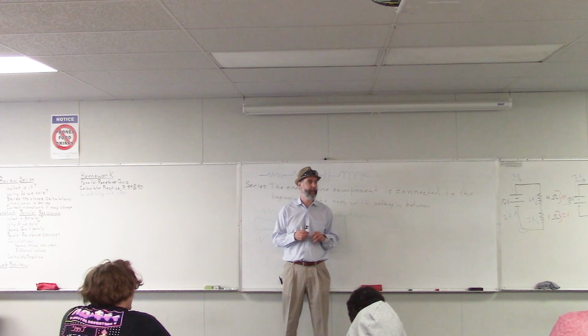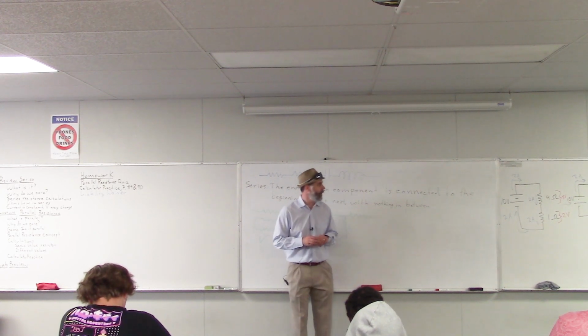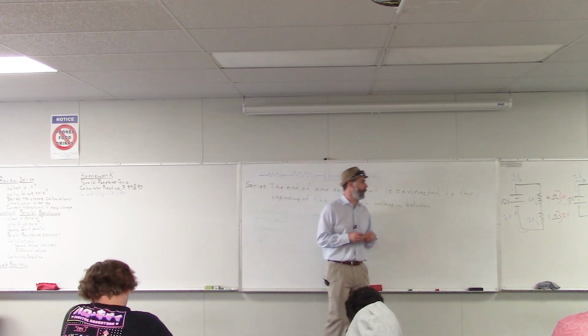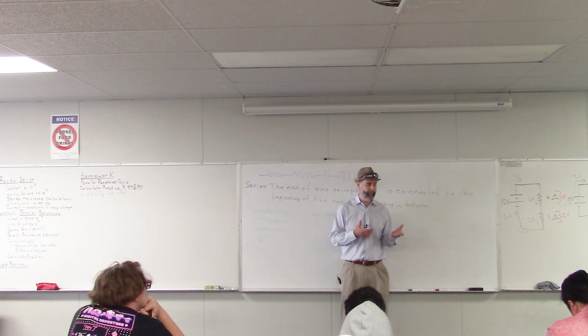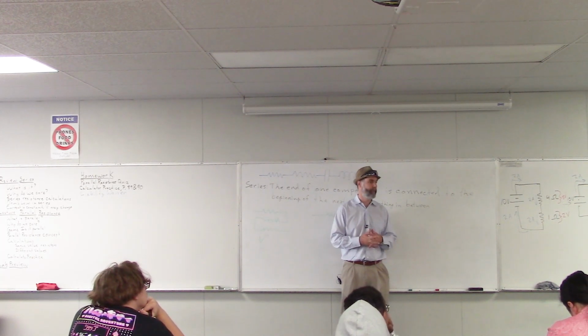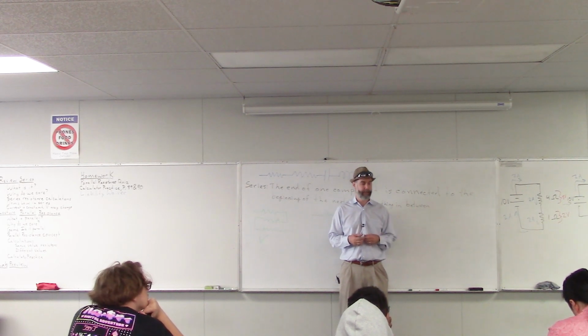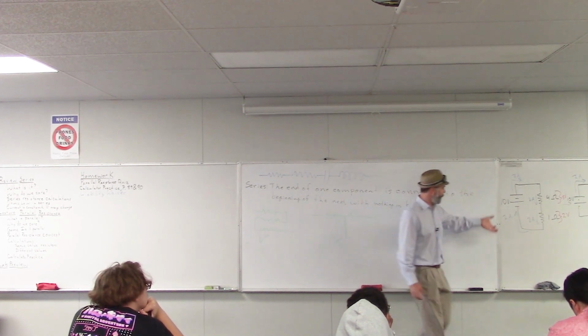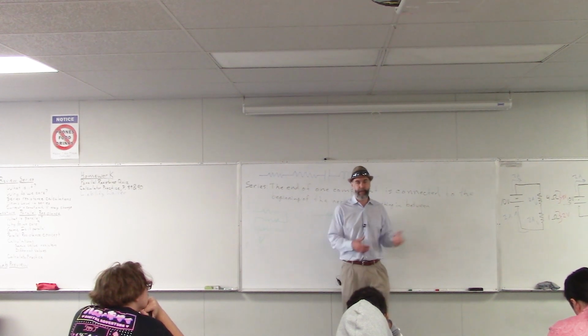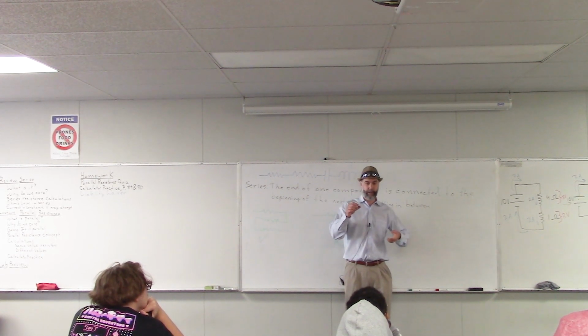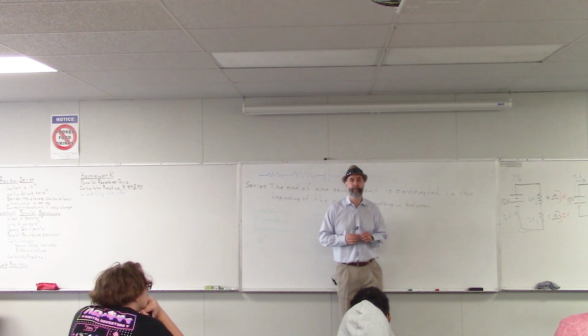Yeah, I think you could. So what would you have to do in order for the voltage to be the same? What would have to be the case in the circuit? Resistors have the same amount of ohms. Exactly. If you have a circuit where all of the resistors have the same value, and you have the same current flowing through each one, then the voltage across each one will be the same.